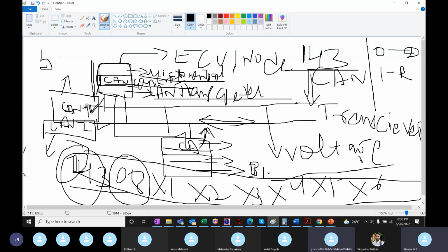That 5 voltage comes when it goes to the microcontroller. There will be a power regulator which regulates it. That is not for the CAN bus. That 5 voltage you are aware of is different; it's not for the CAN bus wires. For CAN high it's 3.5 voltage, and CAN low it's 1.5 voltage.